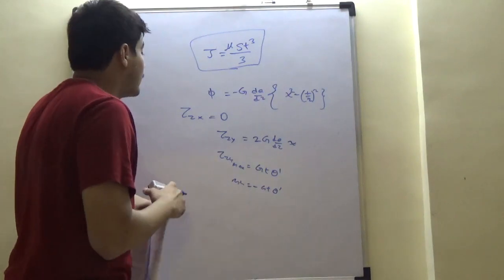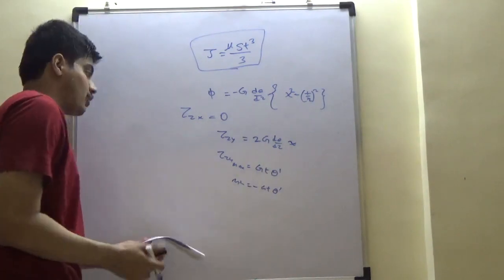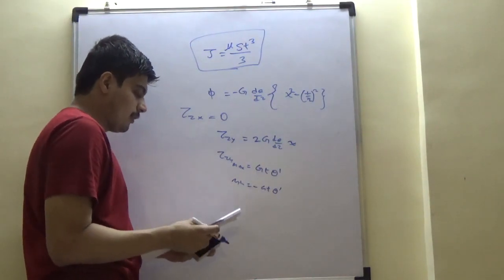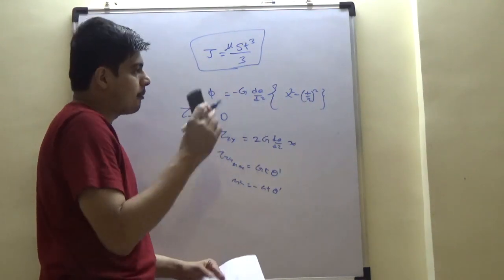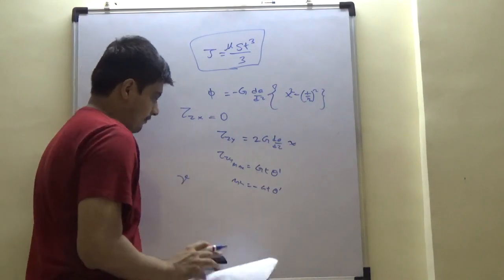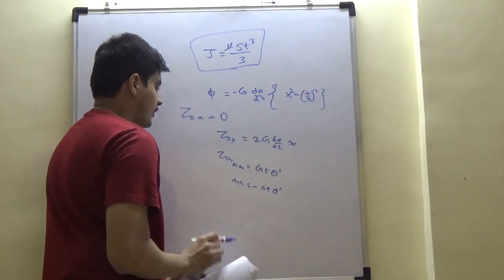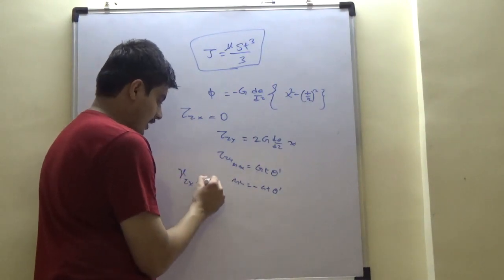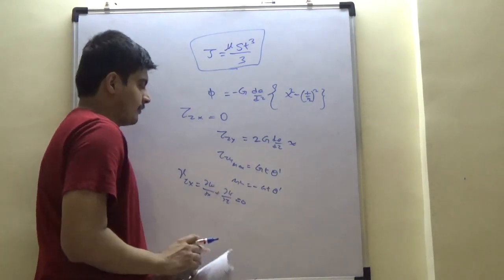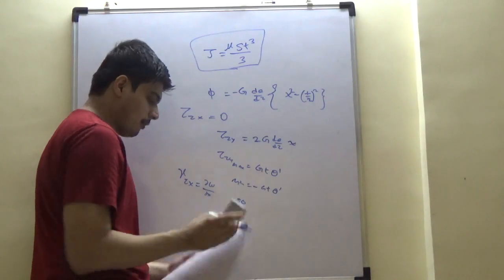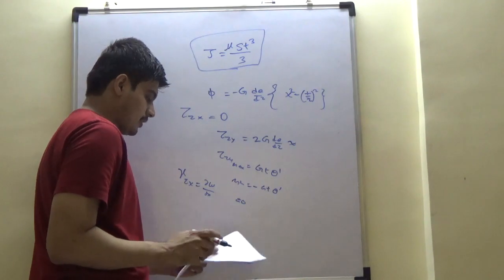So we have defined phi, we know the stress variation, we know the inertia. Now we have to find out warping function, right? How will you find a warping function? To find out the warping function, you need to go back to your definition of gamma, right? Tau zx is 0, which means gamma zx, which is del w by del x plus del u by del z is 0. Del u by del z anyway is 0, so del w by del x, right, is what I am interested in.